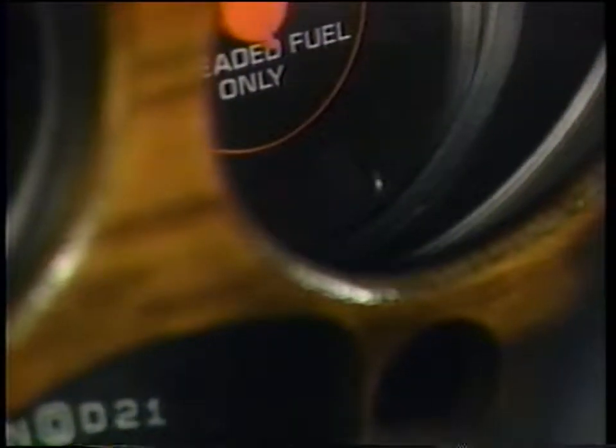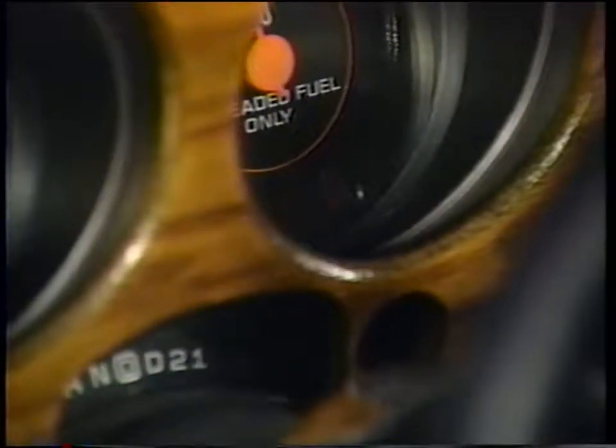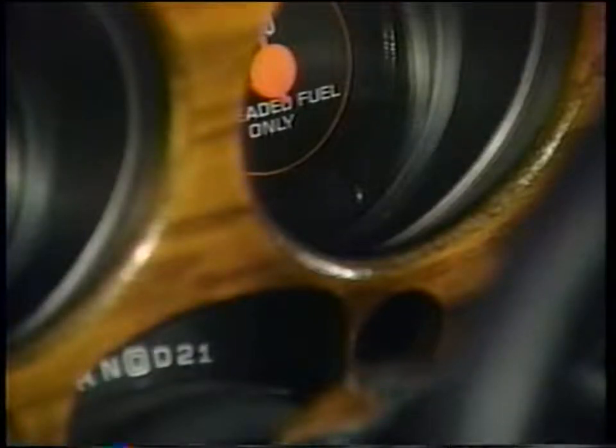For example, start counting when you see the last long flash. Now, add the following short flashes. 1 plus 8 equals a code 9. The code will repeat, so read it at least 3 times to make sure you count it accurately.